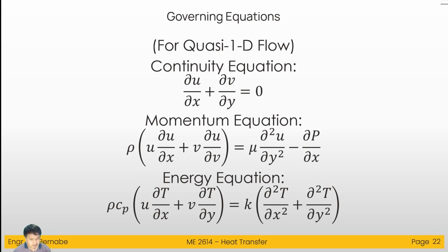So you can imagine the first application of this that you can relate with. You might ask, how do they simulate, for example, water simulations? How do these simulation programs also represent the temperatures of certain scenarios? We can use these equations. But this is actually still a very simple equation compared to what can be used, because this is just one dimension flow. Actually, this is two dimensions since we have two space variables, but frequently we say that this is quasi one dimension because only one velocity is dominant over the other. Anyways, this is also called the Navier-Stokes equation, these first two equations. The energy equation will be just the heat equation.